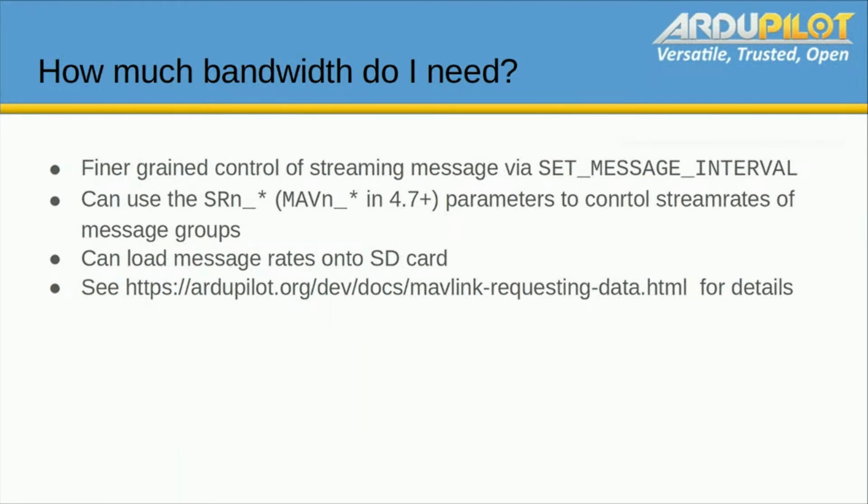You can have finer grained control of what MAVLink messages you want to send. ArduPilot will send many tens of MAVLink messages by default for everything from batteries, sensors like GPS, IMU, any other sensors you've got attached, as well as general system performance. In some cases, you may not want all of this data. For example, you may not want to know about the raw IMU values 4 times per second. So there are several ways to have more granular control of what MAVLink messages ArduPilot can send.